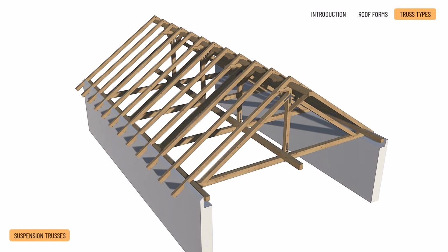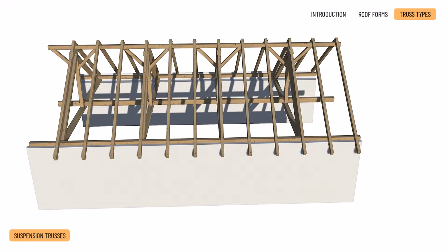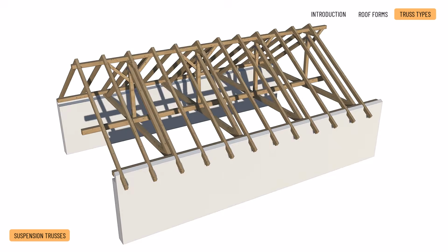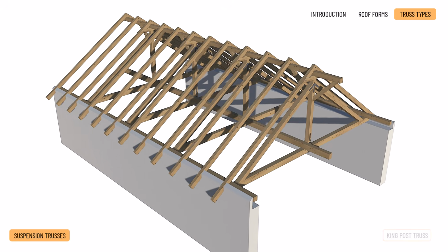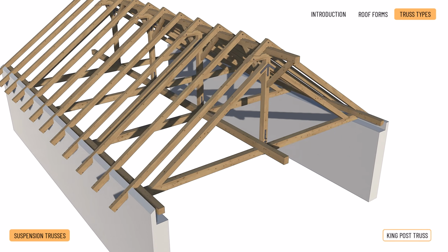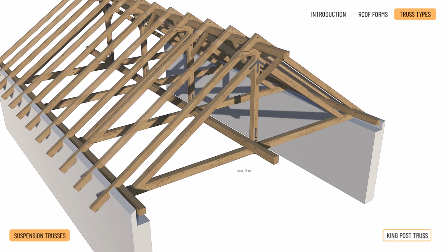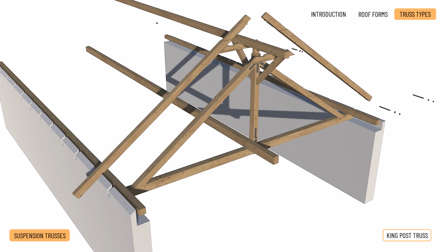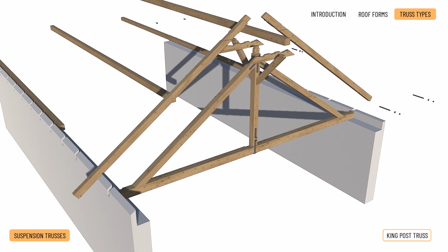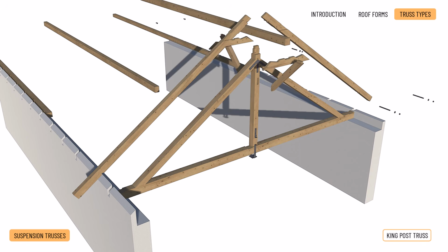Suspension trusses. Suspension trusses use tensioned beams and suspension posts to support horizontally positioned tie beams. In the past, this solution was used when it was not possible to provide column support. King post trusses span up to 8 metres. Suspension posts are installed at the principal trusses between the tie beams and the ridge beams. At the top, the post is hung by a stud bolt between the collar tie pairs, connecting the rafters with a dovetail lap joint. At the bottom, tie beams meet joist hangers bolted on the suspension posts.